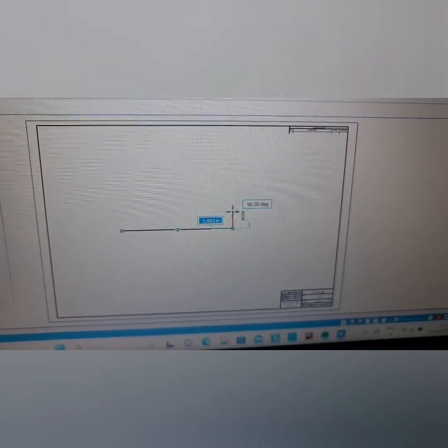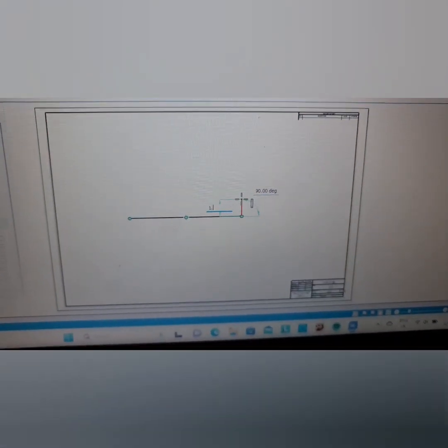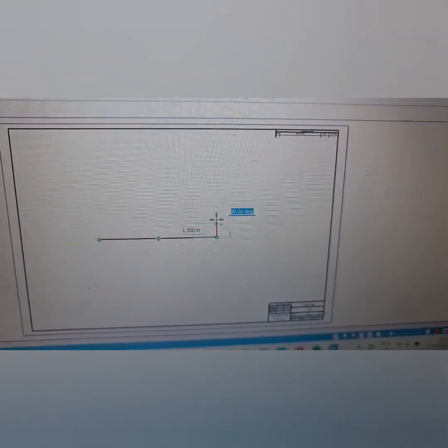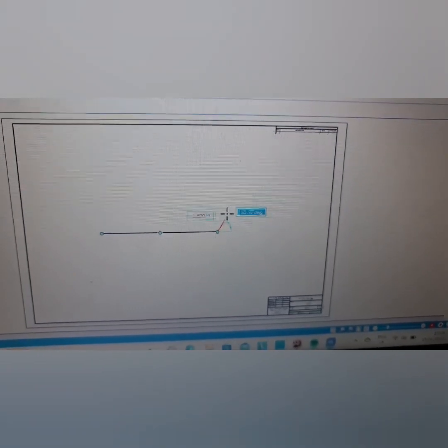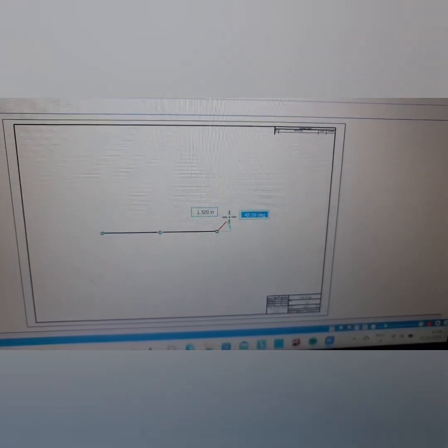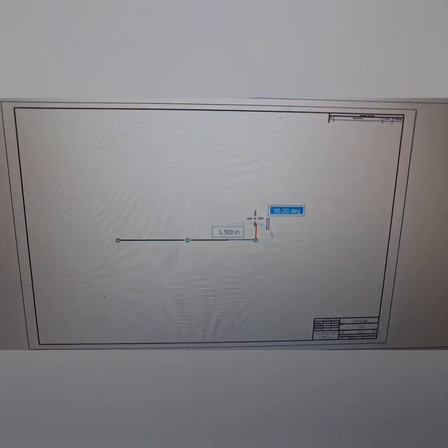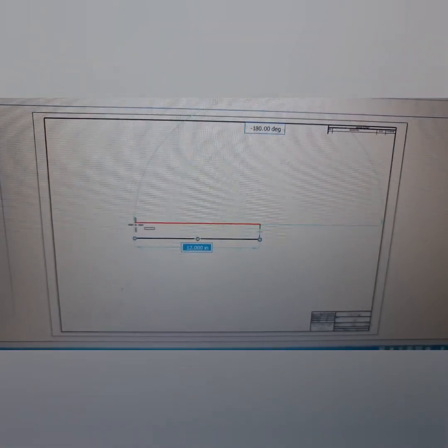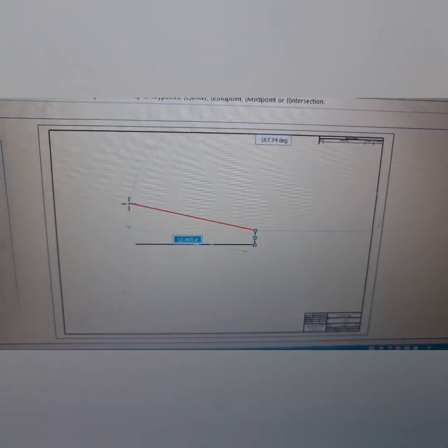So we know our headstocks are 38mm tall or 1.5 inches, so 1.50. Boom, that's the next bit. And now I've set the length of it, it won't change where it is, but I want it obviously 90 degrees to that. Plonk the next bit. As you drag it along, you can put this next one, it hasn't defined its length, but there, see how it's picked up automatically.